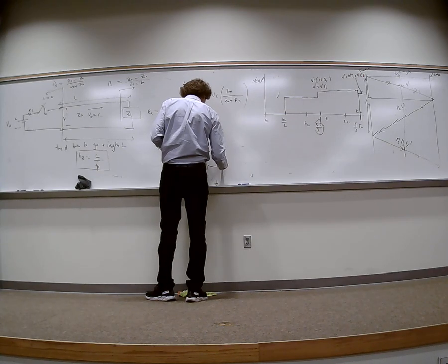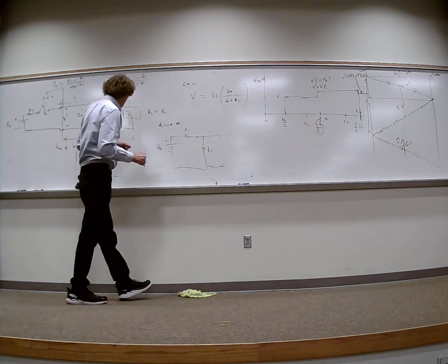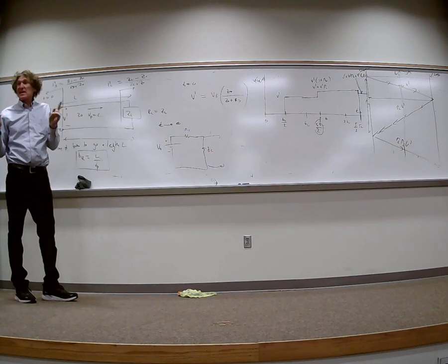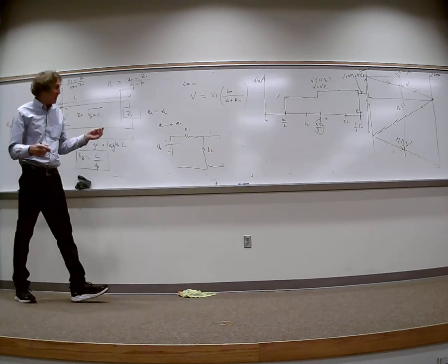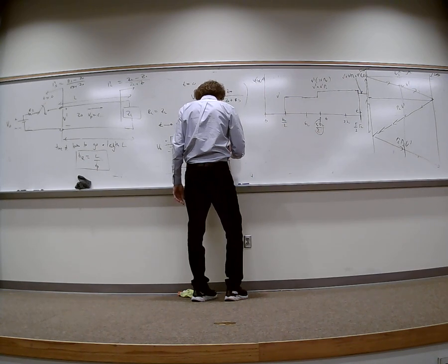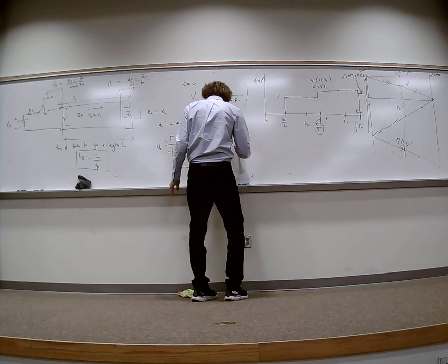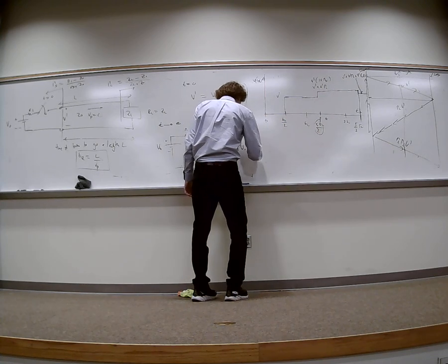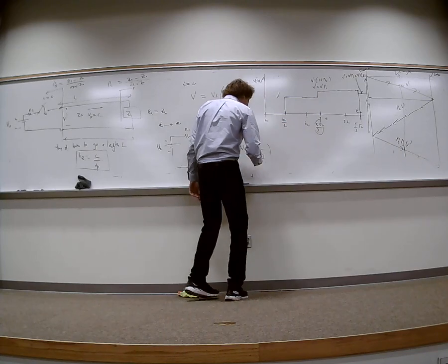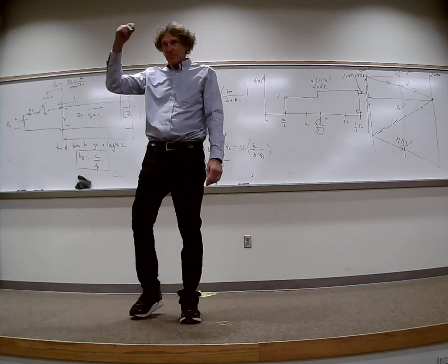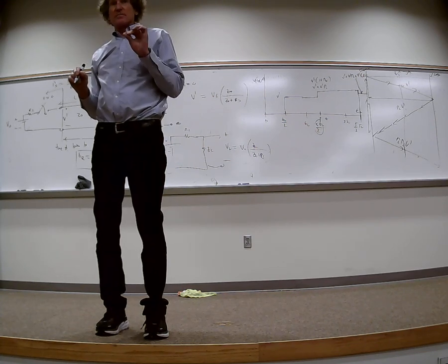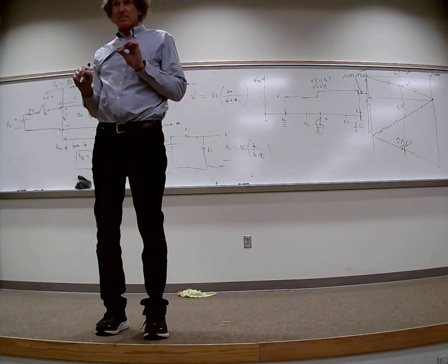So the voltage that will be on the transmission line is the voltage across this load. Now this transmission line looks like a couple of short pieces of metal. Think of it that way. So what's this voltage going to go to? Asymptotically, it's going to go to simply, and I'll call this V load, is equal to V0 times ZL over ZL plus RS. That's how you know you're on the right track. When you take a look at the bounce, it's going to asymptotically jump up and down and then settle at this value, anywhere on the transmission line. You with me on that?